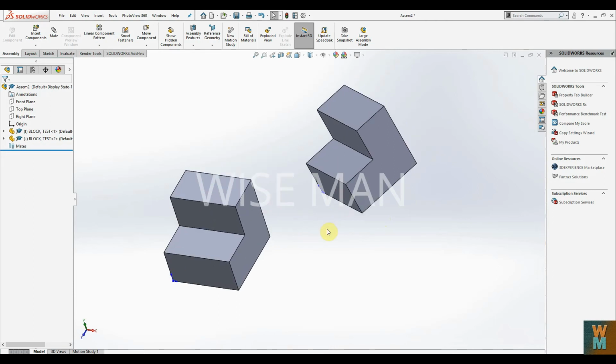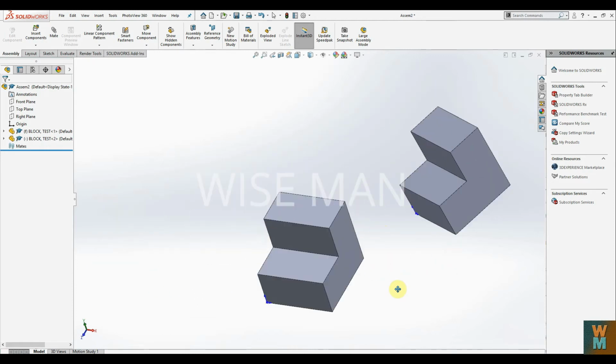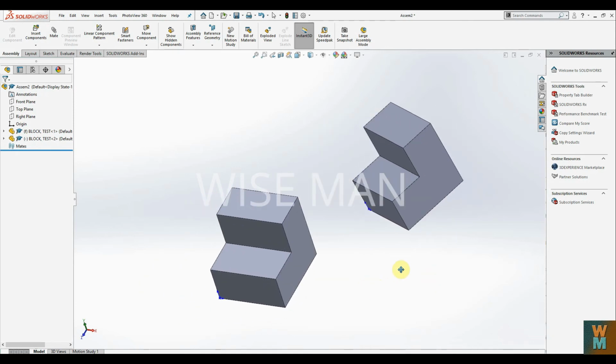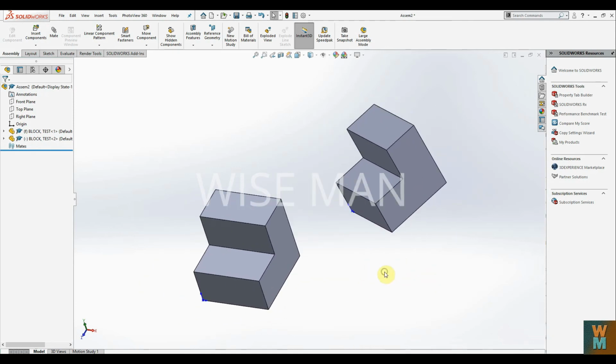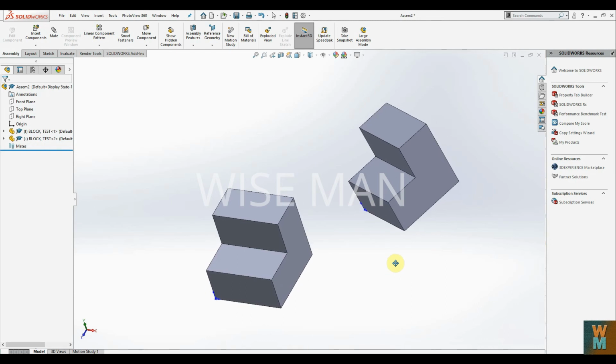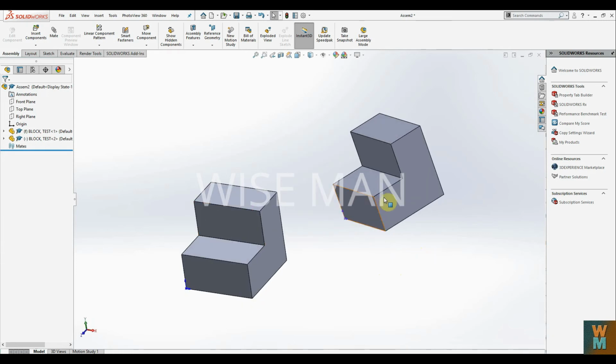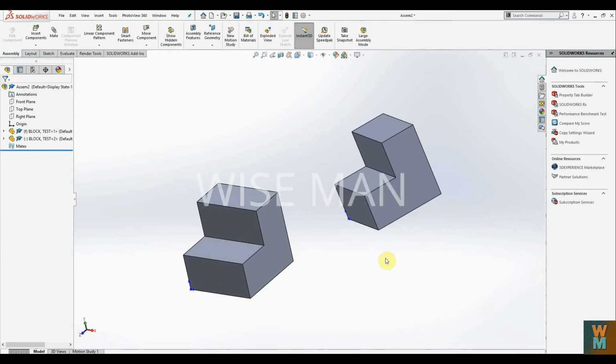If you press Control, and hold the mouse wheel, and move the mouse, you can see that you will move the whole assembly. So by pressing Control and the mouse wheel button, you can move the assembly, and just by pressing the mouse wheel button, you can rotate the whole assembly. So these are the two shortcuts which you can use for your assembly file.